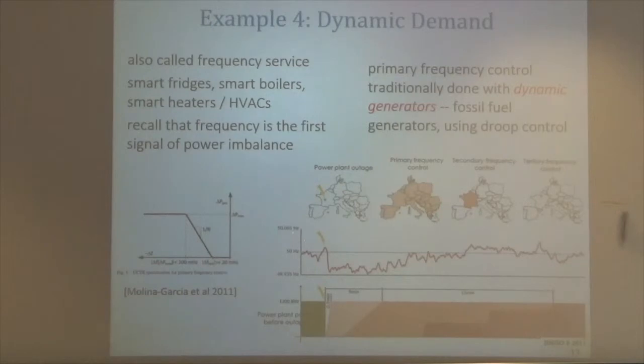Now it's minuscule, it's a few percent of frequency excursions, but it's considered large for an interconnection. So all systems in Europe will compensate by increasing their power by using what is called droop control. All other systems from Spain to Poland will produce more. So they drive faster, if you want, until they re-establish the frequency.